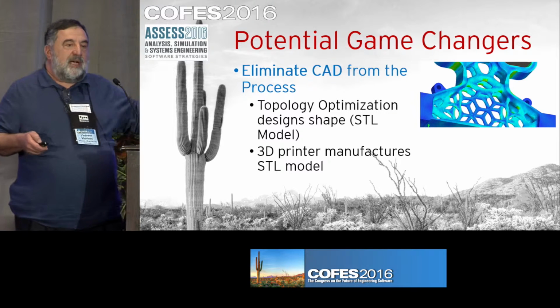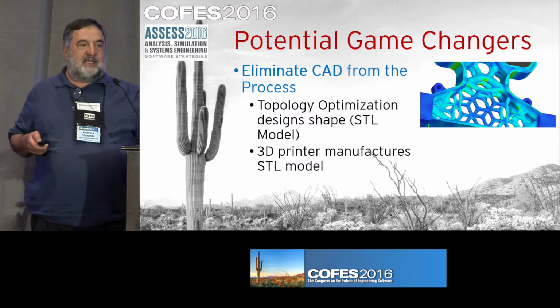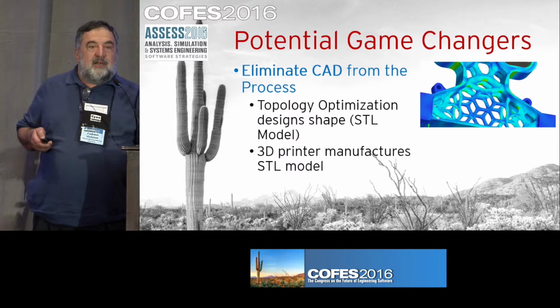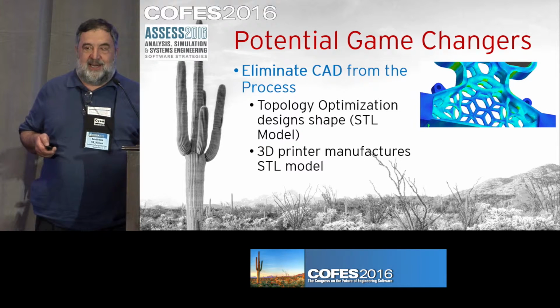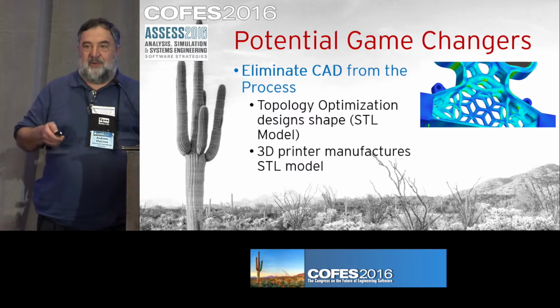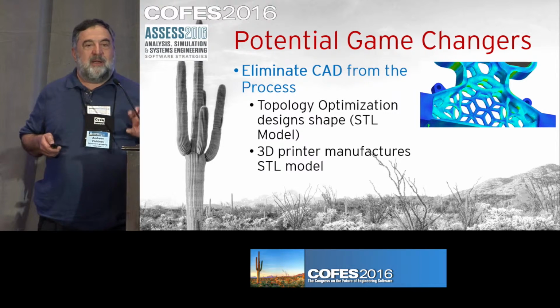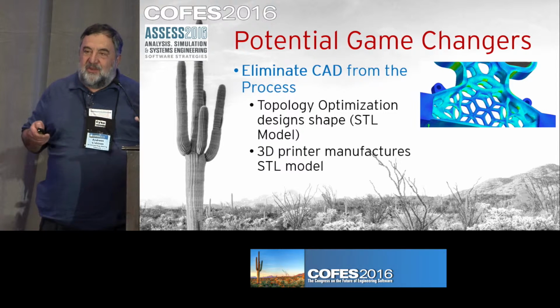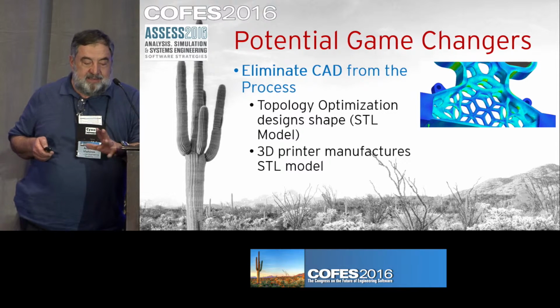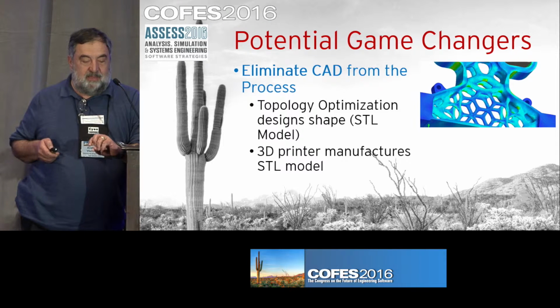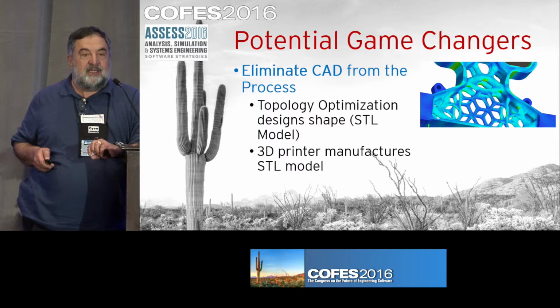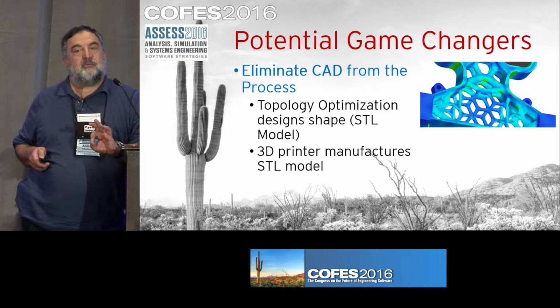Yeah, but I can't give the customer, if it's DOE or the defense industry, an STL part when they need to do, for example, tolerance analysis or tolerance stack-up, or put GD&T on it, or know where the ball bearings are with accuracy. So it's a very broken process. Topology optimization straight to printer is not quite acceptable yet. But look, from the photos you can see we have really fantastic designs. We can save up to 70% of the weight.